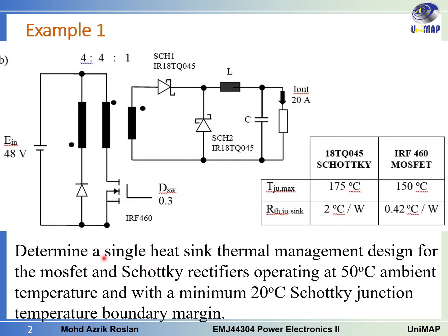So what does it mean by having a single heatsink thermal management? The single heatsink means that we have three components that are switching. This is the Mosfet, and these are the diodes where the current will turn off and turn on based on the switching of the Mosfet.